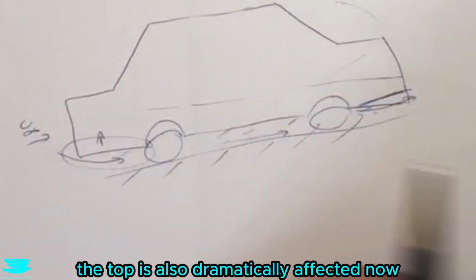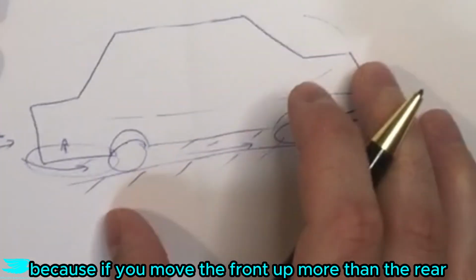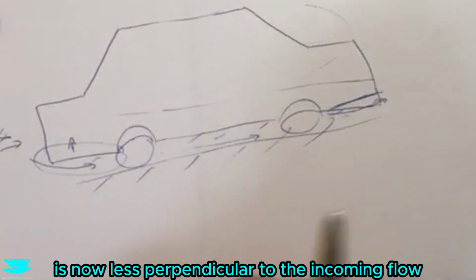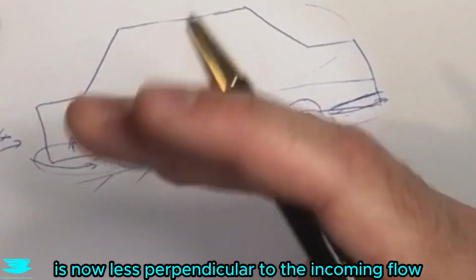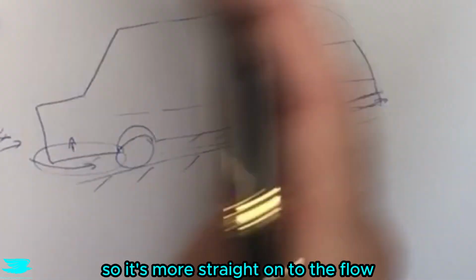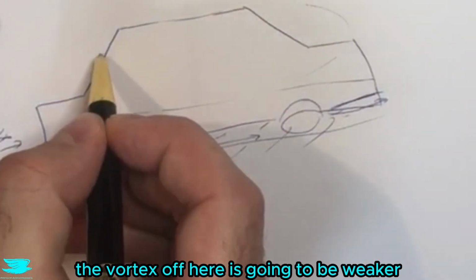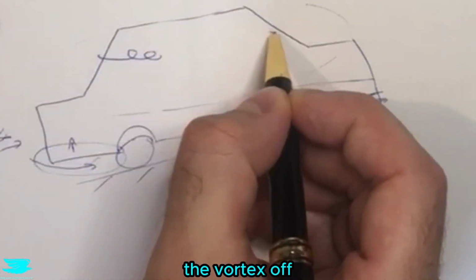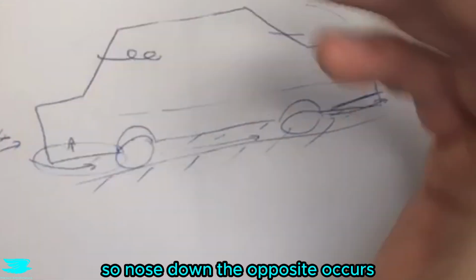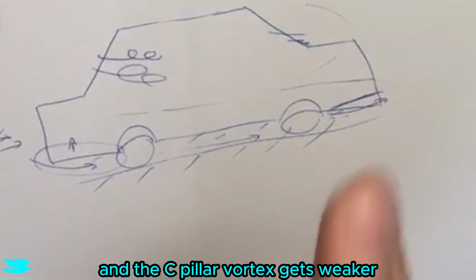The top is also dramatically affected now because if you move the front up more than the rear, so the car's now at an angle, the front A pillar here is now less perpendicular to the incoming flow. The C pillar is more perpendicular, so it's more straight on to the flow. That means the A pillar, because it's more at an angle, the vortex off here is going to be weaker. The vortex off the C pillar here is going to be stronger. If you were to pitch the car down, so nose down, the opposite occurs where the A pillar gets stronger and the C pillar gets weaker.